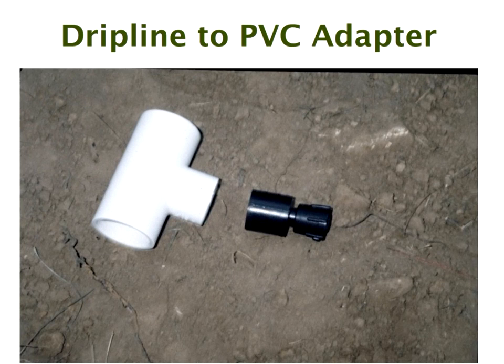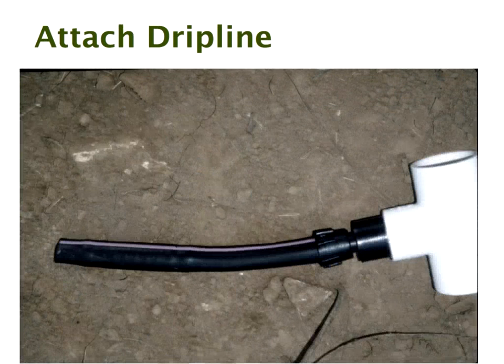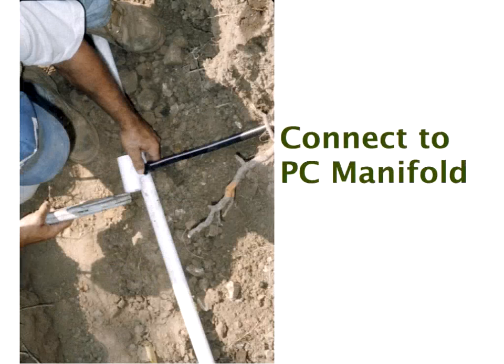All right, let's just go through some of the equipment that's needed for an installation. This is a standard PVC slip adapter, and this is a special adapter that glues into the PVC slip adapter, and this is designed to take a standard half-inch polyethylene pipe, which is mostly the standard that's used for drip line. Okay, and here you see the drip line connected to the PVC adapter.